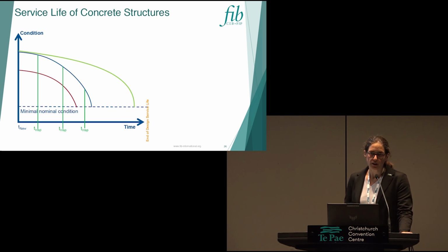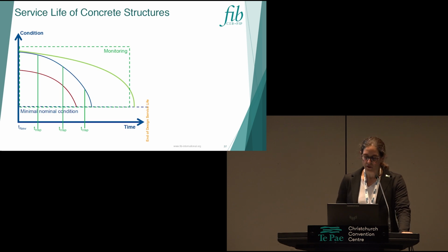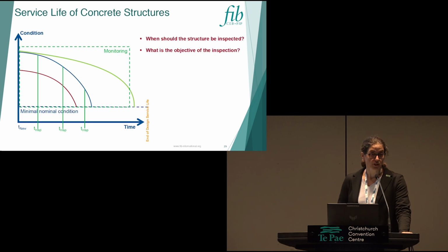Probably in every country it's scheduled a little bit differently. At least in Germany, you have to look every 3 years at any kind of infrastructure. And besides all the inspection methods you can apply, we also have a bunch of different monitoring, and we have totally different questions we have to answer then. So, when should the structure be inspected? What is the objective of the inspection?